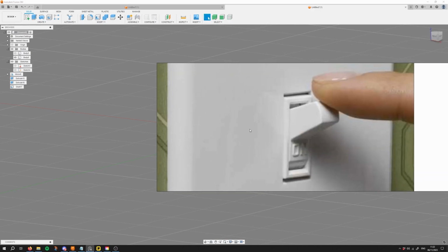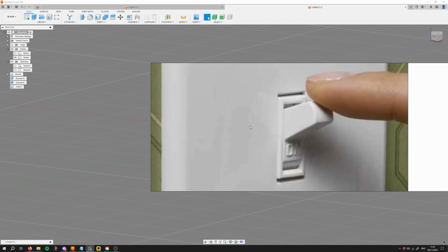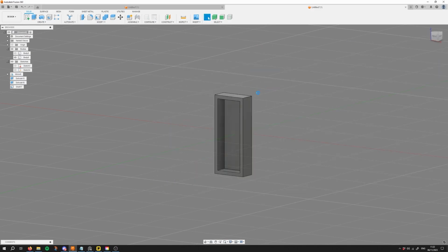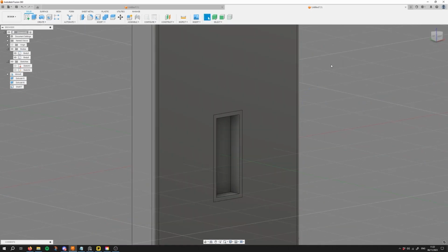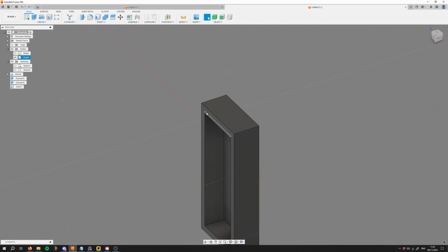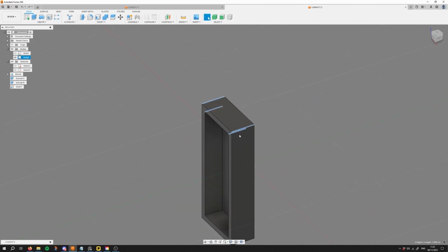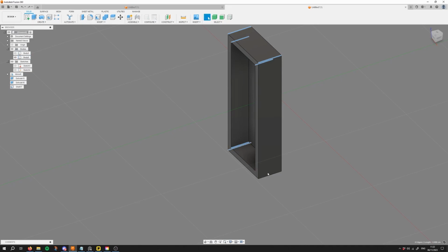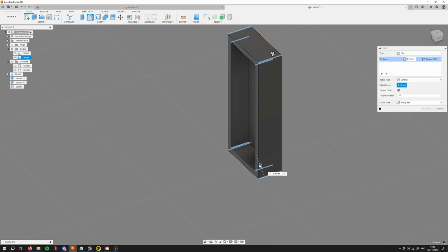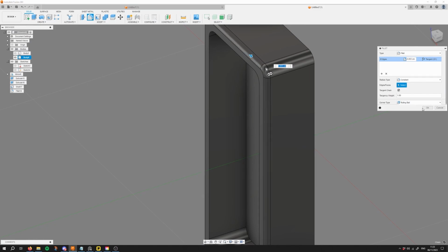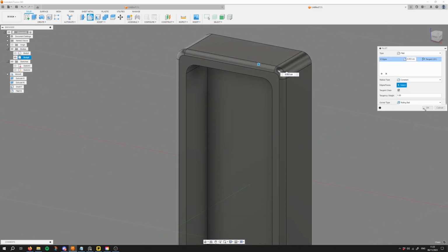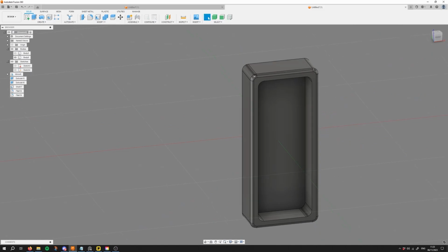Right now, when you unisolate it, it'll be not that visible. So we want to go back and maybe round some edges out. Of course, this is a high poly model, so if you want it to be a low poly, you obviously would not do this. We're going to fillet some edges to make it pop out a little more. And if we're happy with it, we can rotate it, see what's good, press OK.